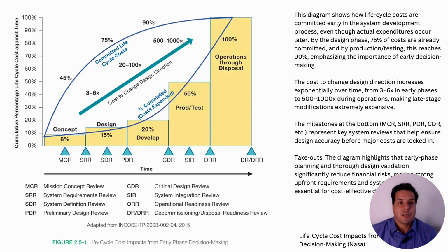A good system engineer recognizes where the energy is required in those moments, because there's limited energy. So if you're doing design and you know that if you change that part of the design later in the stage, it's going to be more expensive than if you change it now, you put the energy to try to improve your outcome at that moment, on the things that you can change later and are not going to be that expensive. I'll give you an example. The type of propulsion of a plane. You're going to use propellers or turbines. Changing that in the design is easy, but later on will be expensive.